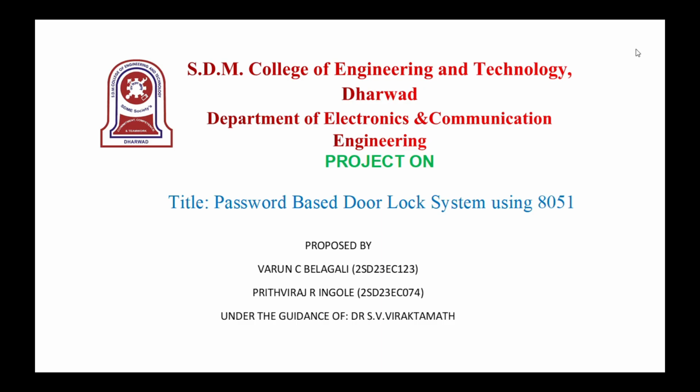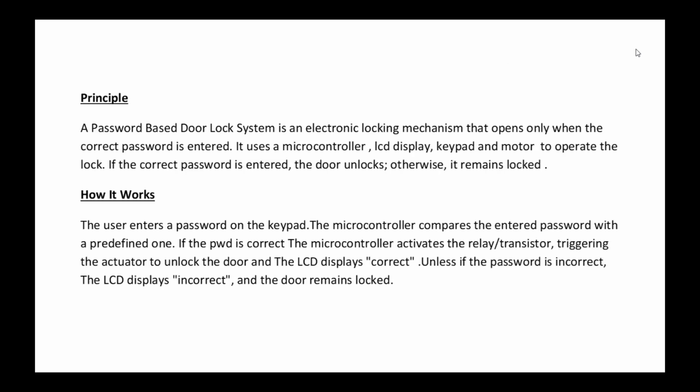Hello everyone, now I am going to explain about the project titled Password Based Door Lock System using 8051 Microcontroller. Principle: a password based door lock system is an electronic locking mechanism that opens only when the correct password is entered. It uses a microcontroller, LCD display, keypad, and motor to operate the lock. If the correct password is entered, the door unlocks, otherwise it remains locked.